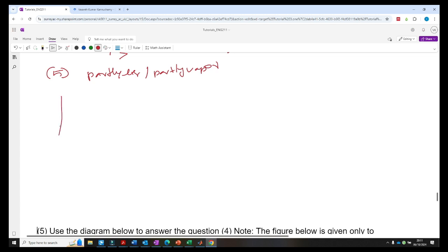So we are just playing the game using the TXY diagram. Okay, so TXY, saturated liquid is here, saturated vapor is here, two-phase mixture is somewhere around this point. Which means the enthalpy of this particular point should be greater than the enthalpy of the saturated liquid and should be less than the enthalpy of the saturated vapor.